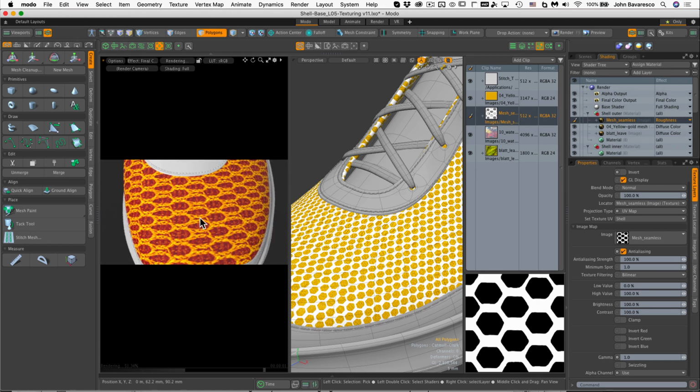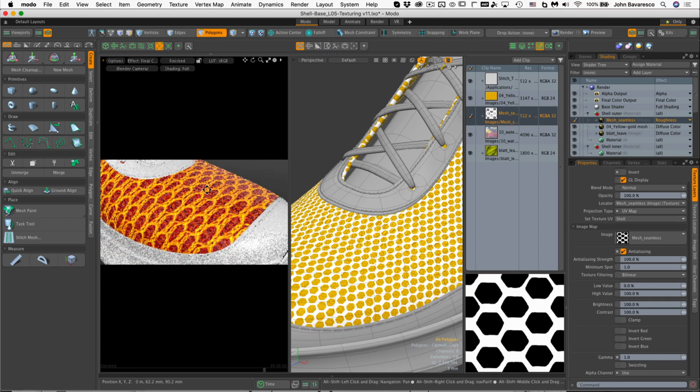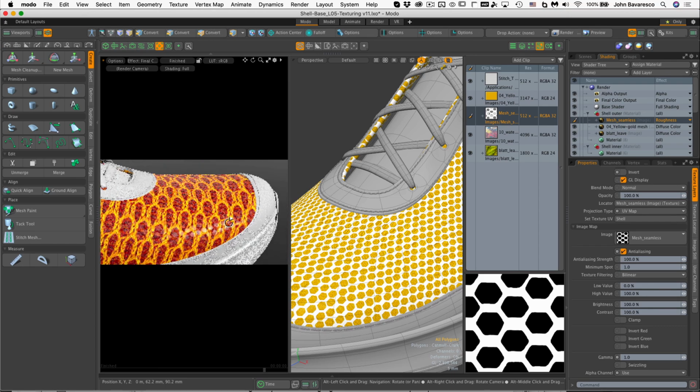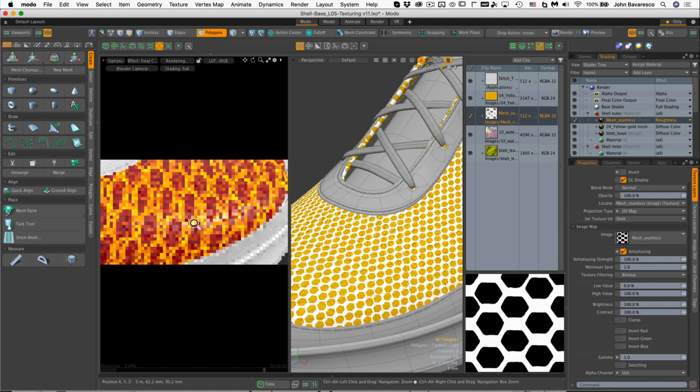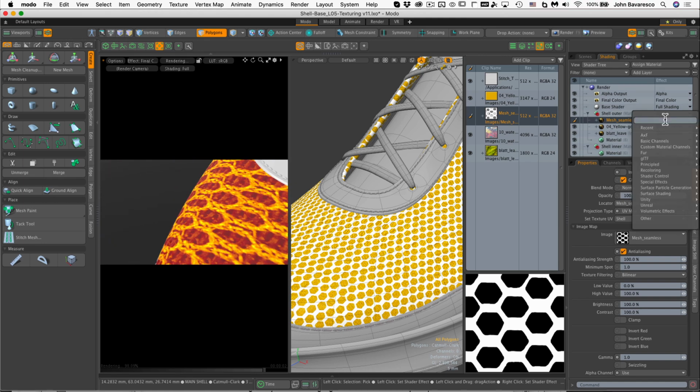Now, like I said, certain attributes of a material depend upon how the light is bouncing off of the surface of your object. And if we look here where the reflection of the light is, we can see how the roughness actually affects that surface. Now, since there are so many different types of attributes or effects that you can apply to your surface, they make it easy by having a search bar at the top of the drop-down panel. You could just simply type in the name of the effect that you are looking for, and let's try something different. Let's try a bump map in this case.